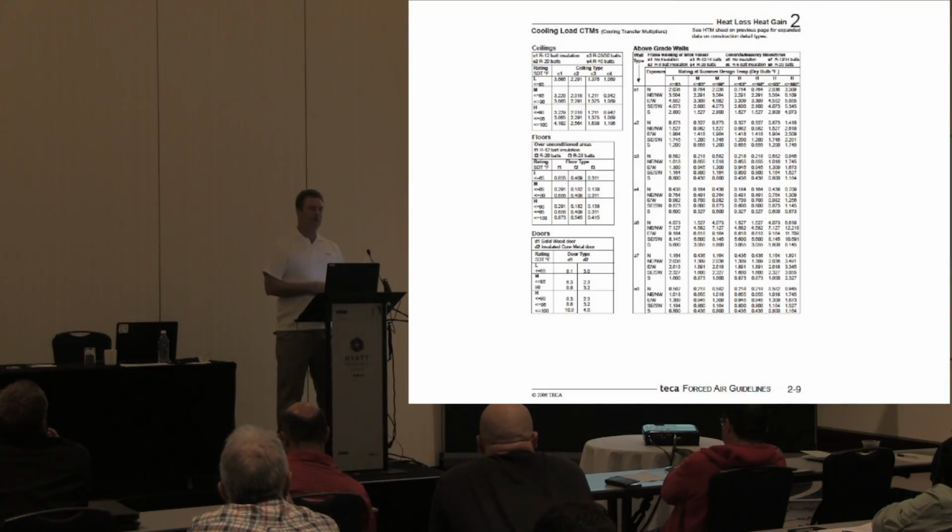But what we want to be careful of, and why I wanted to get this over with, is that a standard heat pump, like a North American built single stage heat pump, loses capacity when it gets cold outside. Some people don't really think about it. They say, well, I'm putting a 3-ton heat pump in, it's 36,000 BTUs, I have 36,000 BTUs. The house only leaks 35,000, I'm good, it'll heat the house, no problem.